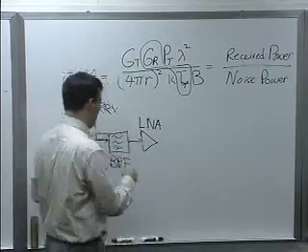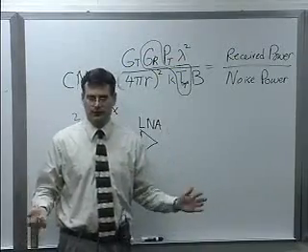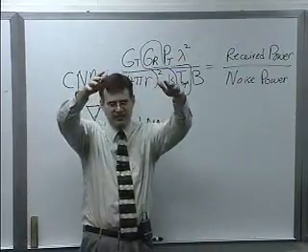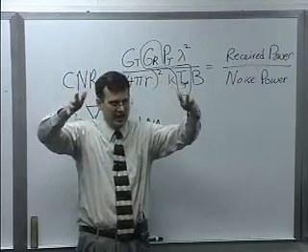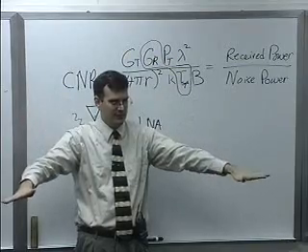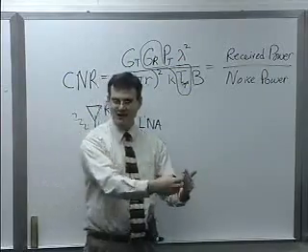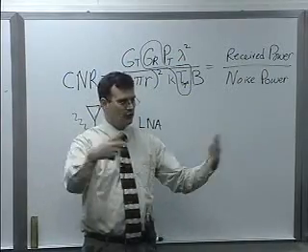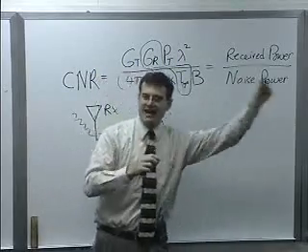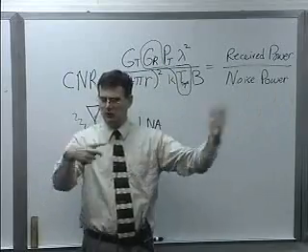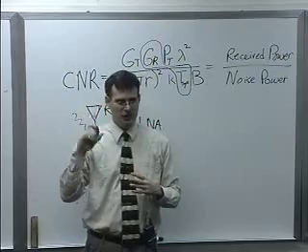So we do put a filter on here, and we have to be careful. It's usually a crummy filter. The goal is just to attenuate anything outside of your desired band by 10 to 20 dB. Because when the cell phone gets close to the receiver, 1 meter of path loss is so much less than the 100 meters or 10 meters from card to access point that has to be communicated, sometimes with obstructions, that it can really overwhelm your amplifier, even a relatively small transmitter.